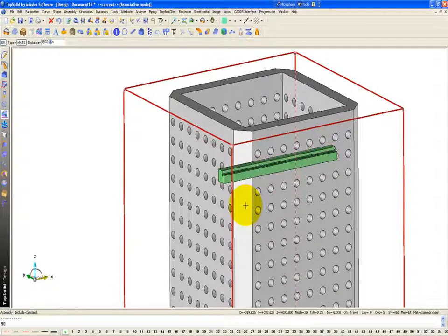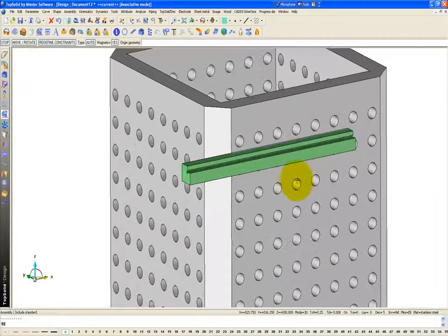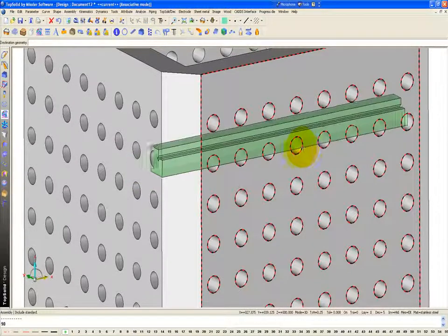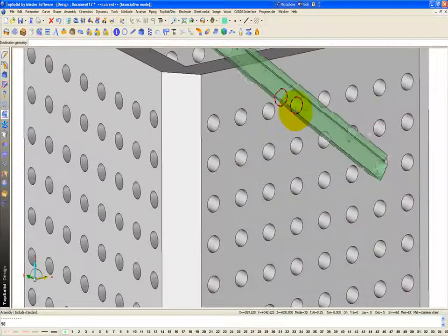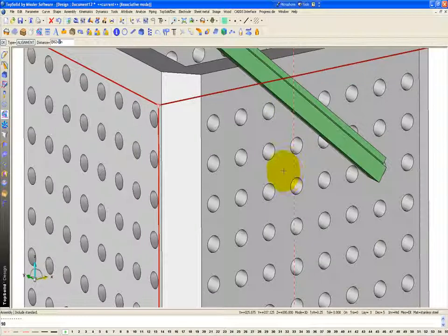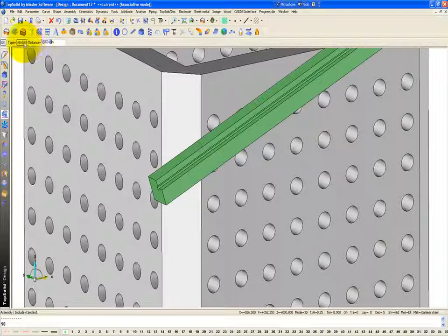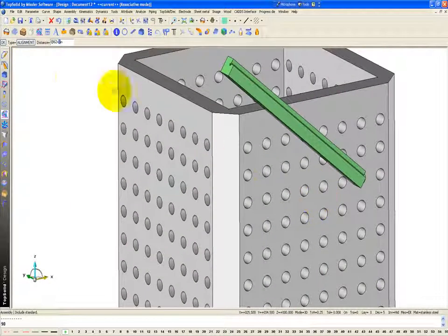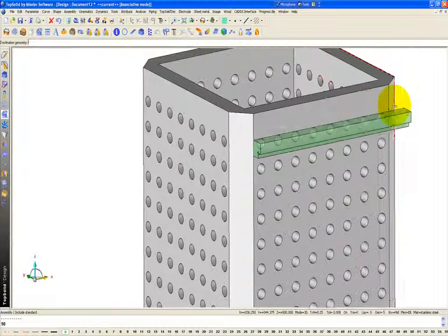Okay? Now, I'm going to say OK. I'm going to select maybe this bottom face here and bring it to one of my fixture pins. Maybe I'll bring it to this top one. Okay? And what I want here is an alignment. No, maybe I want to mate. Well, we'll keep it alignment. Why not? The next thing that I want to do, I'm going to say OK, is take this face to this face.